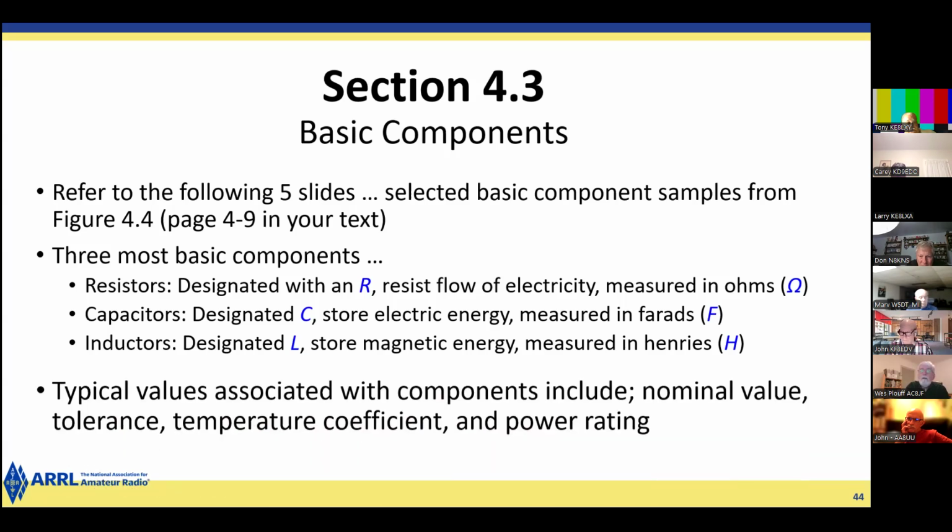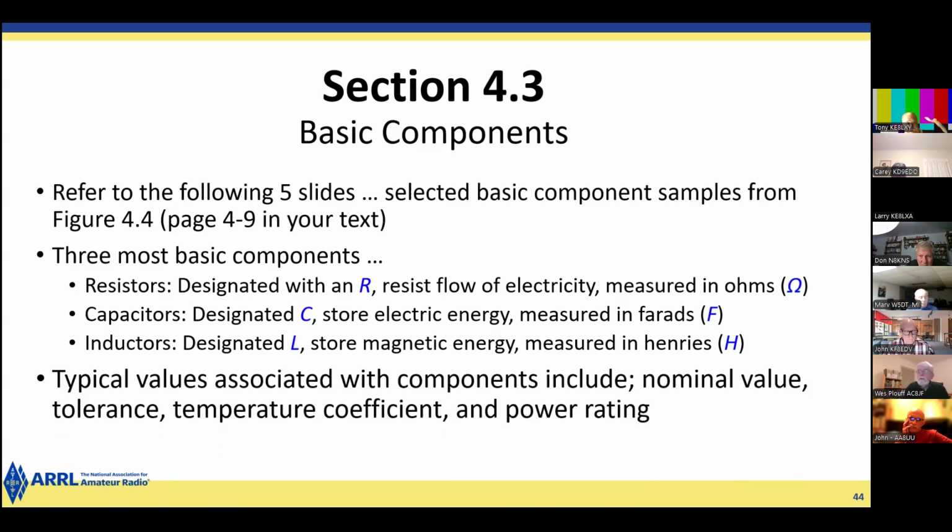And then practical components include ratings such as the nominal voltage, the tolerance, the temperature coefficient. In other words, how much does the value of a component change as it warms up or gets cooler, and the power rating for the component, so you don't blow it up.